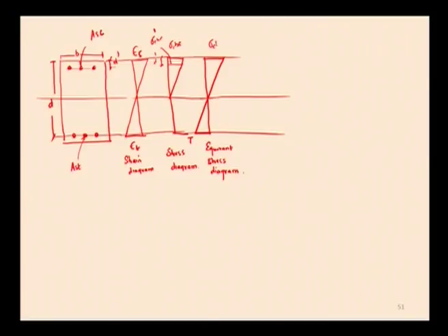So, sigma cbc is the stress at the topmost extreme fiber, sigma st by m is the stress in concrete surrounding tensile steel. This we have already derived. Now, take this as sigma cbc dash, which is at a distance d dash from the topmost extreme fiber.